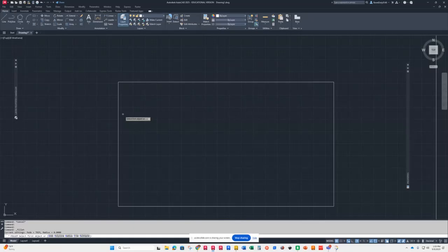Both axles, boom, boom. And that's just what happens. You forgot to set the radius. Oh, that's right. Okay, it happens. I've done it before. So you go into fillet, and the first thing you have to do is change the radius. Why do I make a big deal out of this? Because people don't listen.